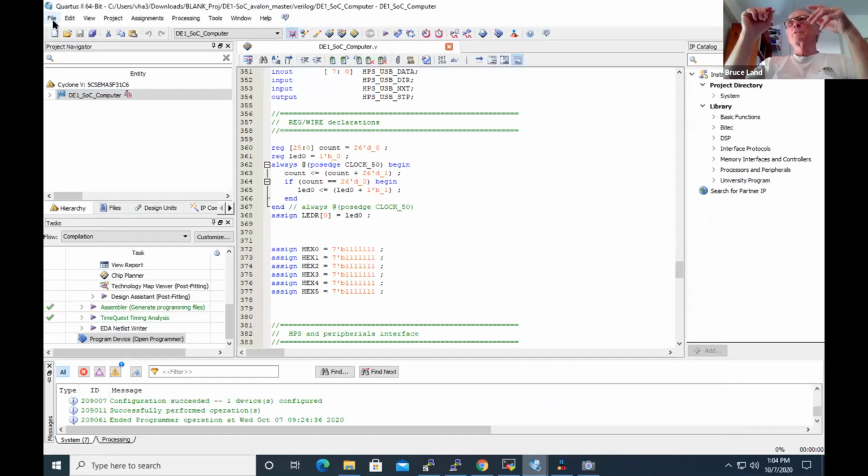That is then integrated and used to control a voltage controlled oscillator, which produces the output. And as a result, you're getting an output signal which is not only frequency locked, but phase locked to the input. That's why it's called phase lock loop.